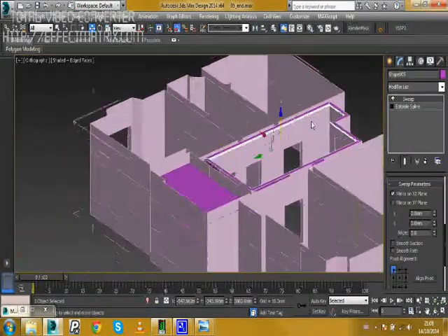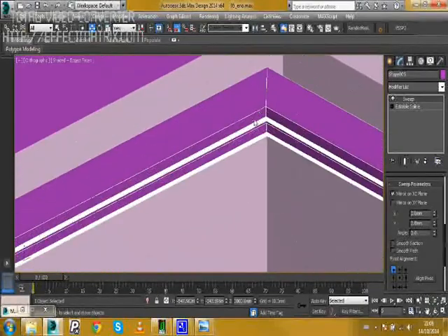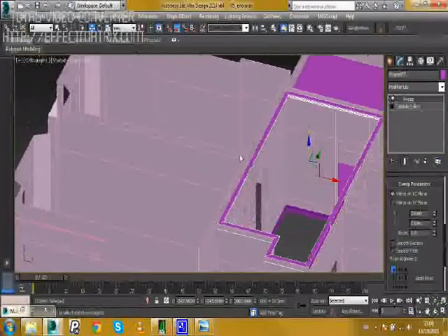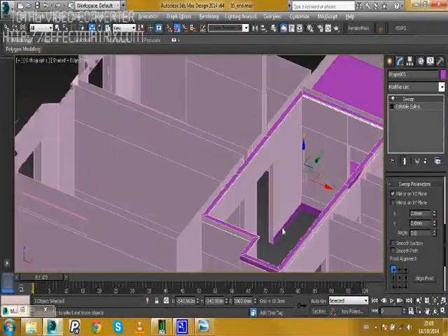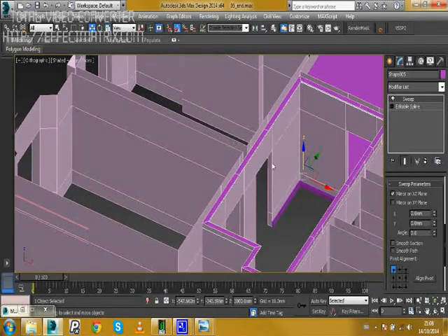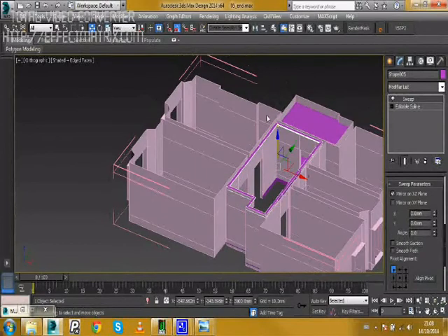We now have our skirting and cornice. And it's just showing you many ways you can edit. You can add these also into the other rooms. For example, the living room, if you see into the rooms in the shots. But it's just the exact same method. Just extract the lines from the walls, use sweep, and select your custom profile which you have created.